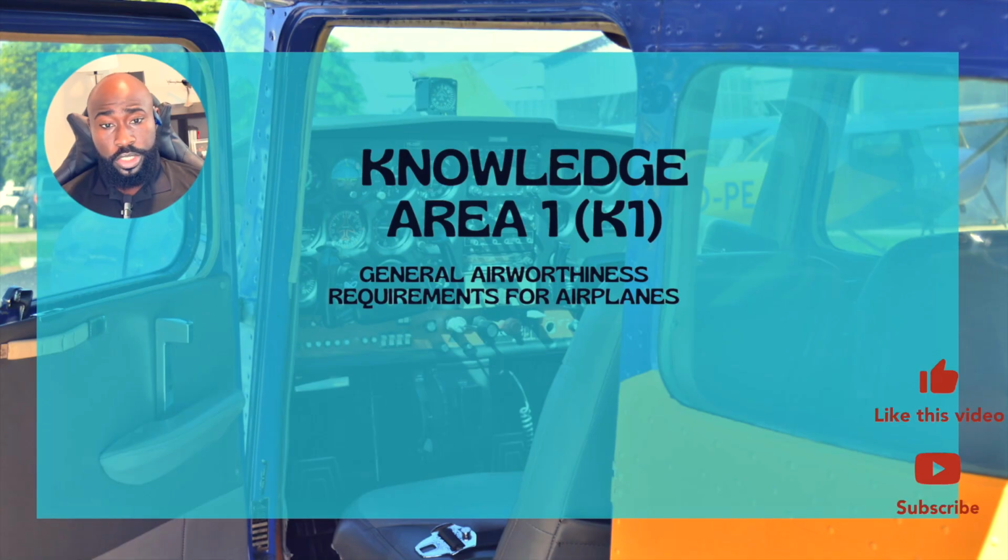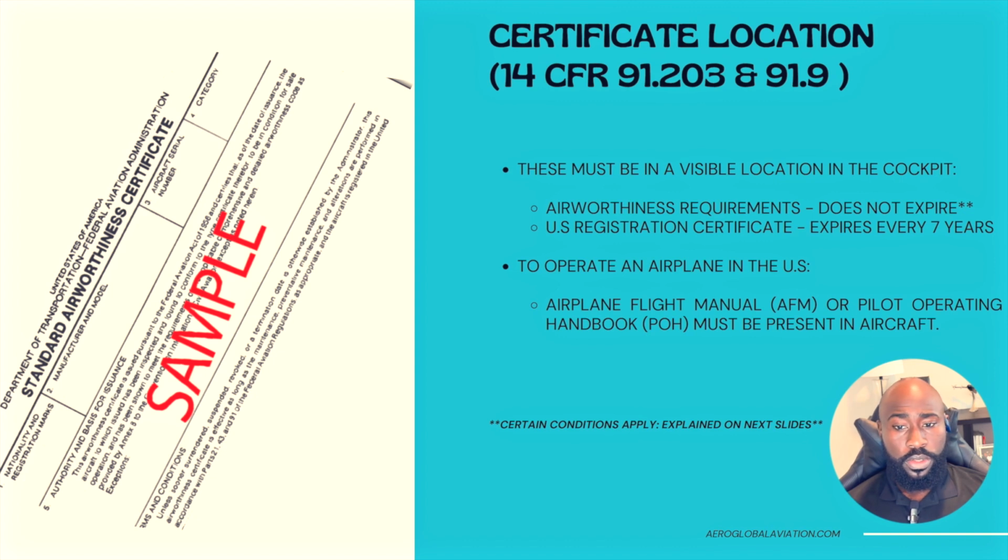We're going to start from knowledge area 1, which talks about general airworthiness requirements for airplanes. The first thing we're going to talk about is the location of the certificates. On the left side here, you see a picture of what a standard airworthiness certificate looks like. This must always be visible in the cockpit. The airworthiness certificate is a certificate that the FAA issues to all owners of aircraft to let them know that the aircraft is actually airworthy, and it does not expire. We'll talk about this in more detail in slides to come.